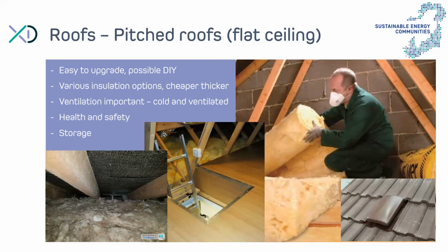Another thing to consider is, are you using your attic as a storage space? If that's the case, you have a number of options to make sure the space underneath that hard surface is insulated, but that you can load that surface sufficiently to store, let's say, your Christmas decorations and that kind of stuff. What we normally do is to put a rigid board across the rafters and lay floorboards on top of that. A simple OSB board would do the job perfectly well.